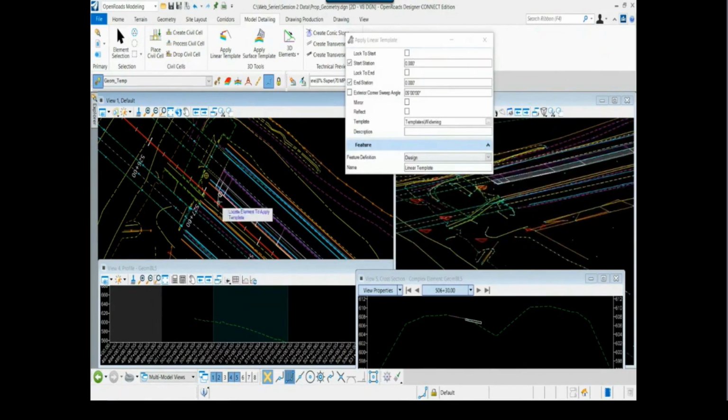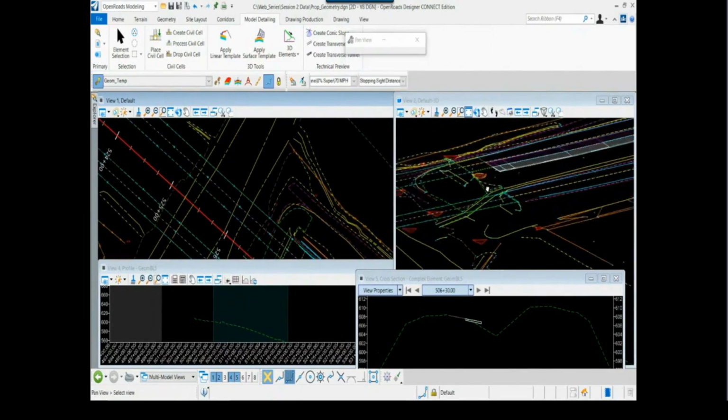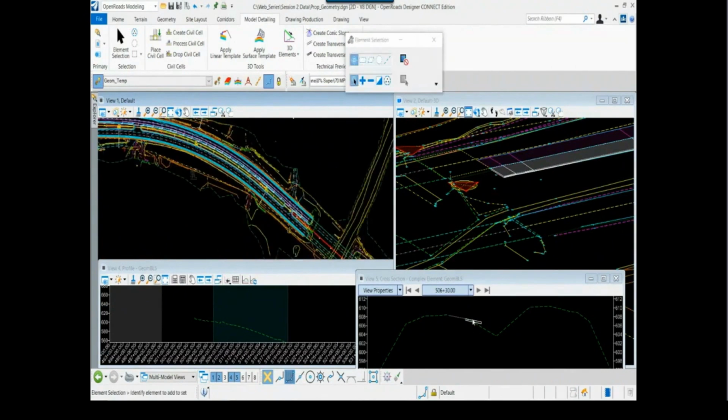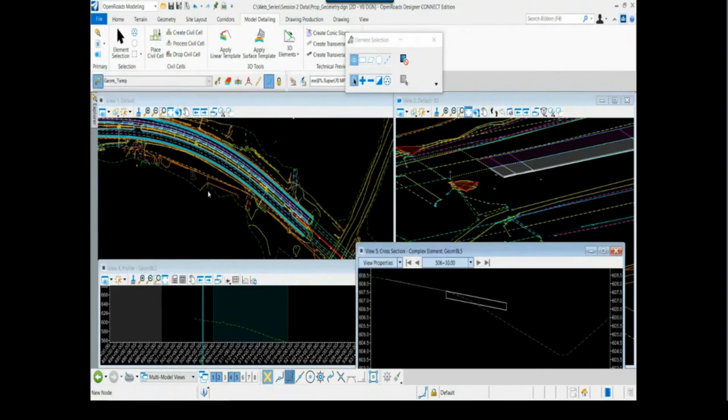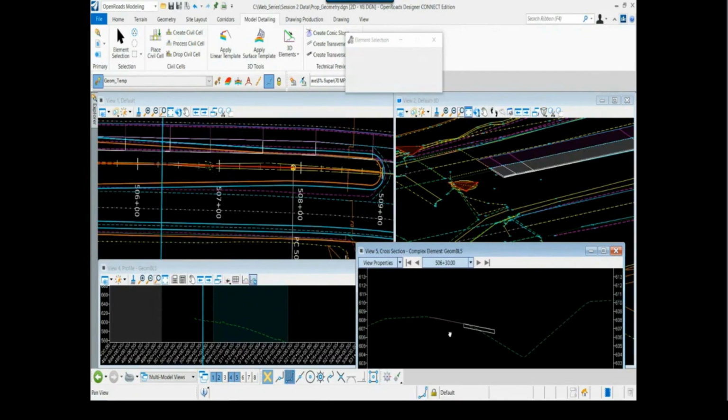We won't worry about the bridge at this point. I'll project it in a different way. But we now see that PGL based off the existing cross slope and widened. Now, I will point this out. In this case, for time's sake, we did not take into account, although we may do this at a later session in a SIG coming up, super elevation correction or milling and overlay. Again, our focus is geometry, so we didn't go through that process. We may pick that up at a later date in a separate SIG session. But we've located now this point that's going to be the basis for what will become our PGL.